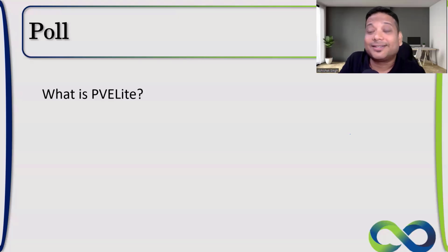Now that result further may need processing. You may not be able to give the decision directly by seeing the result. A few times there is analysis which can give you direct results also, so the methods of analysis are different. But the majority of the time, for the analysis we do, we need to perform lots of post processing. We need to compare, classify the stresses, compare with the allowable. So that is analysis.